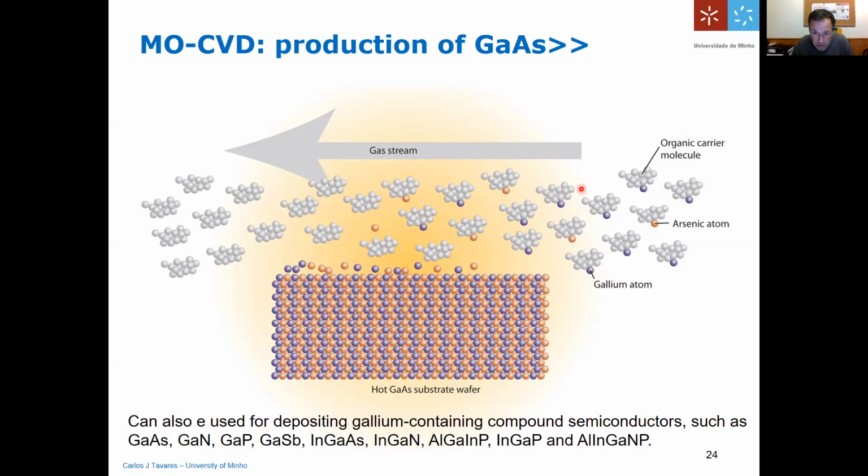And when these precursors fly above your substrate, due to the temperature activation, they will drop these atoms in ordered form, and they will grow monolayer by monolayer with a high coverage and a very good coherence throughout the deposition of these layers. And you will have something like a monocrystal, okay, but on a smaller scale.